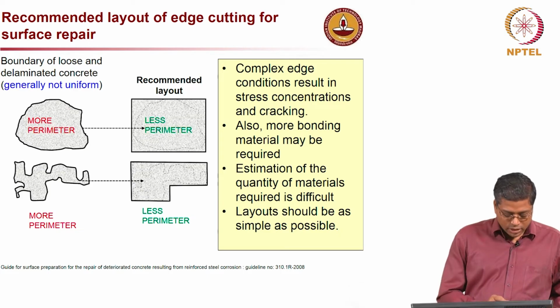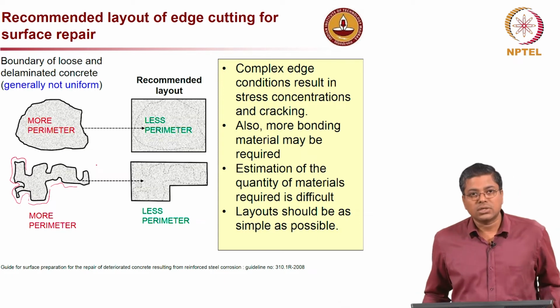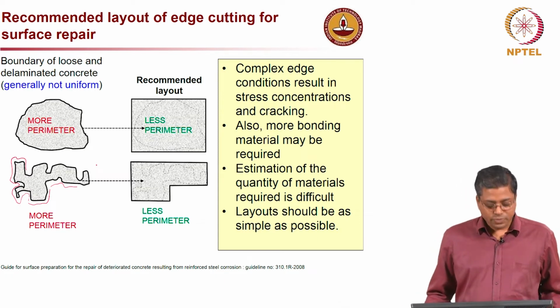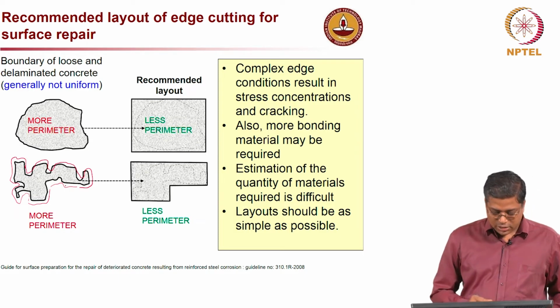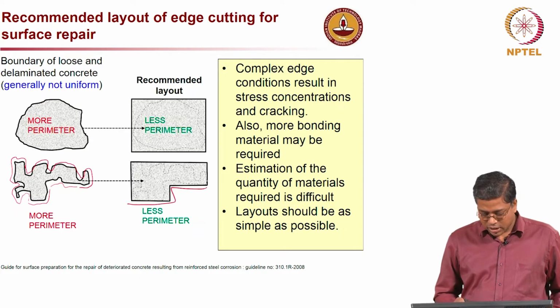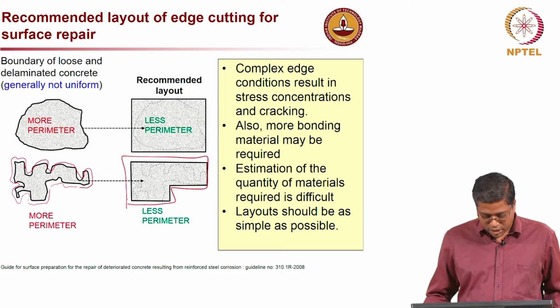But when you talk about repair, if the shape is irregular, look at the bottom left, there are a lot of regions where stress concentration can happen, and also the perimeter of this surface in this case is much larger than if I make an assumption and cut something like this, as you see in the bottom right.